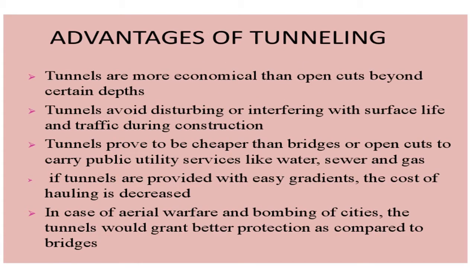Now coming to the advantages of tunneling. Tunnels are more economical than open cuts beyond a certain depth. That means when cutting through rock becomes very difficult beyond a certain depth, then tunneling can be more economical. Tunnels avoid disturbing or interfering with surface life and traffic during construction. Tunnels prove to be cheaper than bridges or open cuts to carry public utility services like water, sewer and gas.